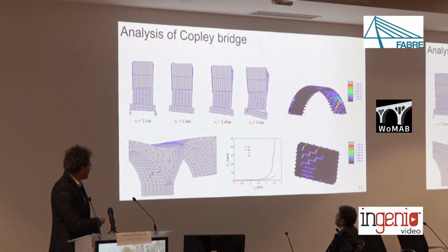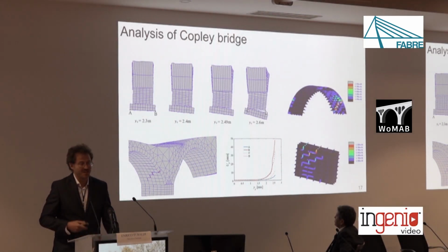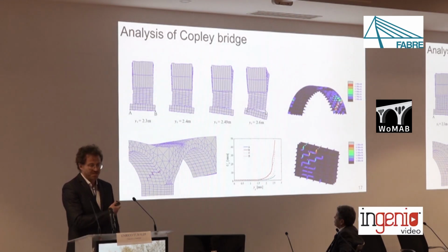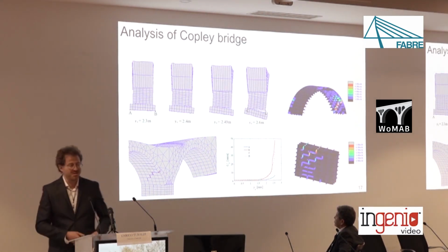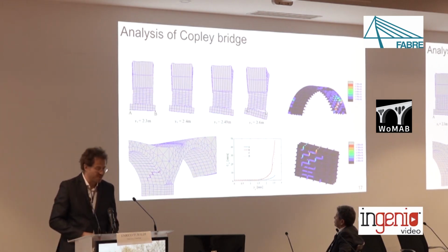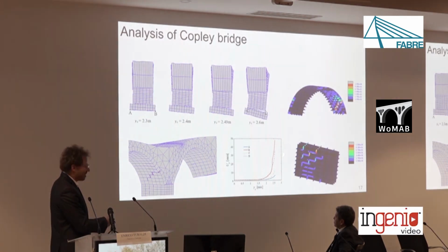And then all of a sudden, when you start to undermine the foundation from below, for small increases of scour, you observe a very sudden increase of the response. So this is a displacement response, but if you monitor the crack opening, or you monitor plastic deformation, if you use a model in Abaqus, or other response parameters such as rotations, you will observe very similar trends.